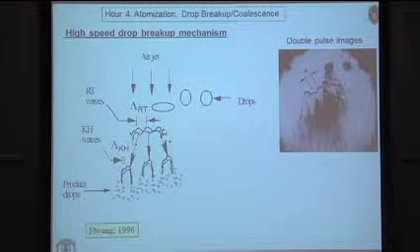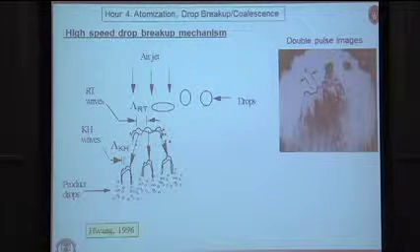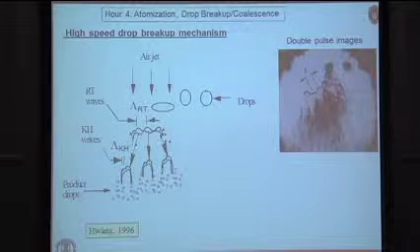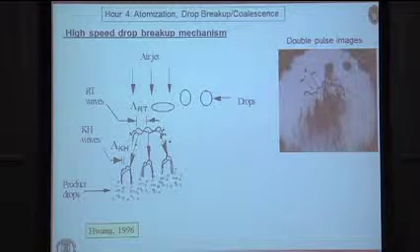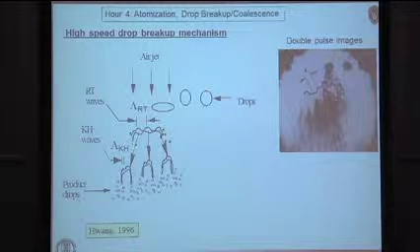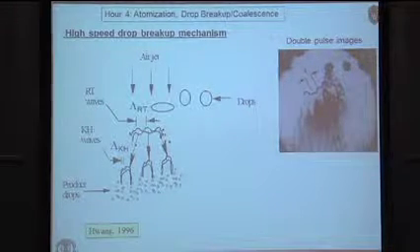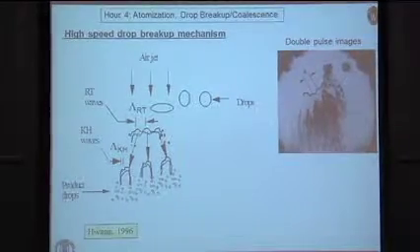But if you go to the other extreme, where you're now looking at very high jet velocities, or gas velocities, and by the way, the relative velocity in this case is more typical of what you would see in a diesel application, you see these type of pictures. So here we took those same pictures. Now those drops are actually coming in from the right. Here's the drop before it encounters the air. And these are double pulse pictures. The exposure duration was very short, a couple of nanoseconds.